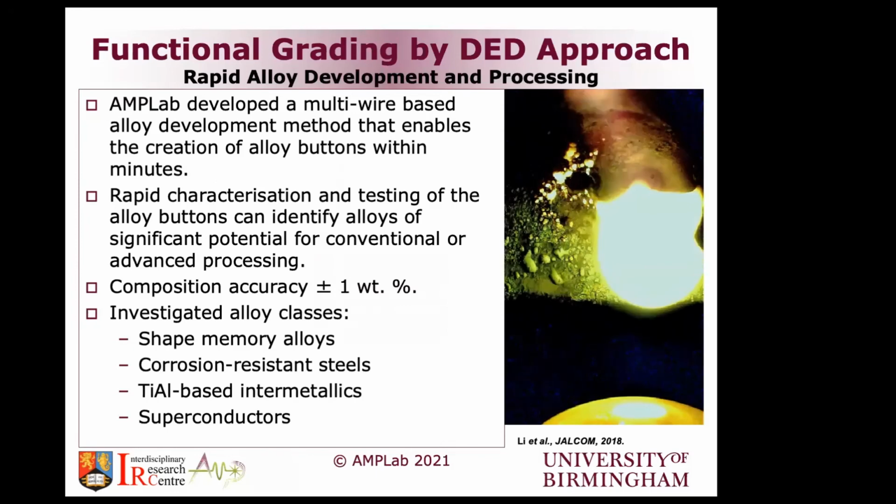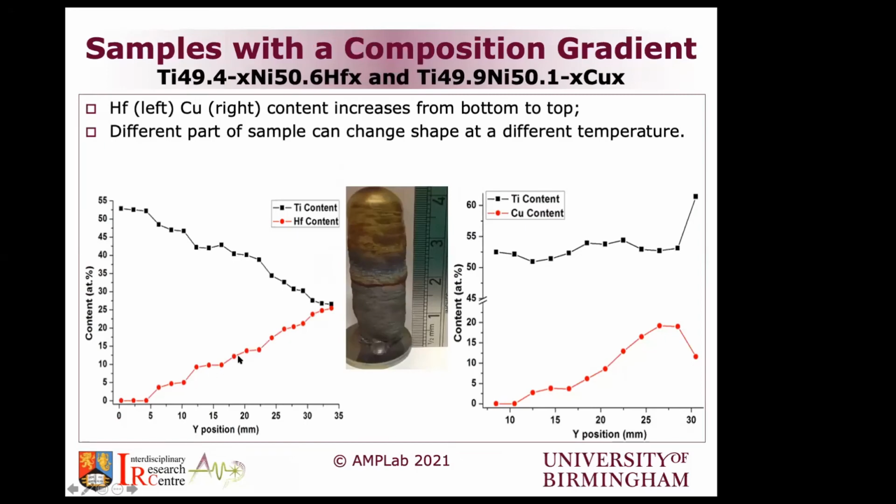So when you look into the chemical analysis, despite everything, we do get a nice linear variation of the element because of the way the process itself runs smoothly. You just keep reducing one and increasing the second. This is how it runs. Now, in these two systems specifically, we did not experience cracking, obviously induced by the intermetallics, as your question was probably asking. But in other systems, we saw that, yes.